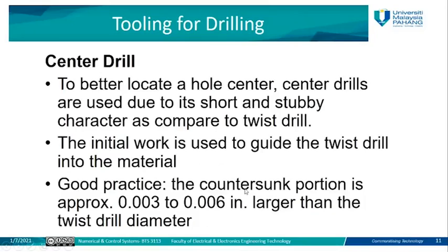The second type of tooling for drilling is the center drill. The center drill has a different shape compared with the twist drill. It depends more on the torque that will be generated from the center of the tool. Okay. The initial work here is to get the center of the hole; it is used like a guide for the rest of the drill to go inside the hole.